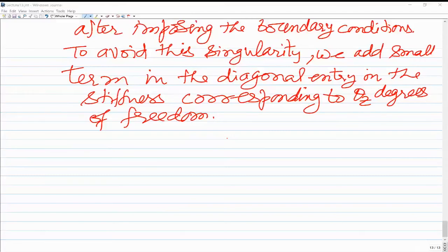So you'll have to update that. You need to make that change. Although I started with 5 degrees of freedom, to account for theta z, although it will have zero contributions everywhere, that has to be added in the nodal degrees of freedom and the elemental degrees of freedom.